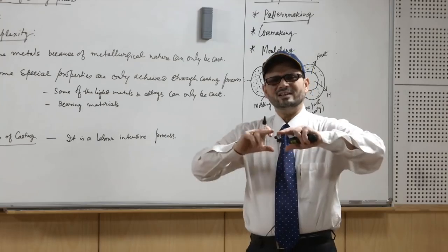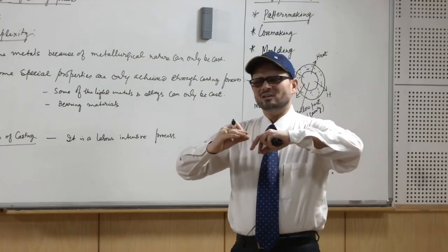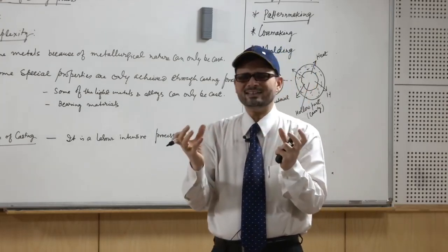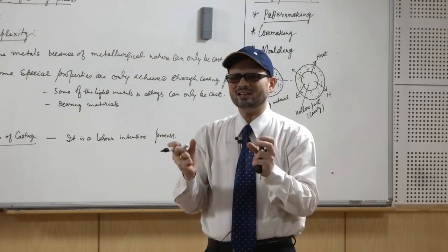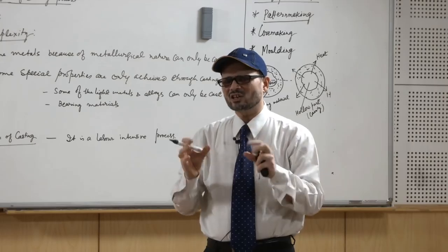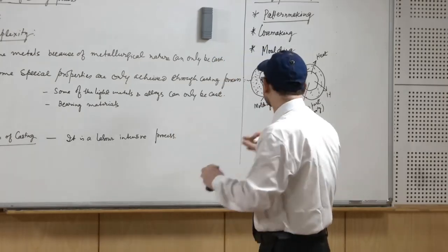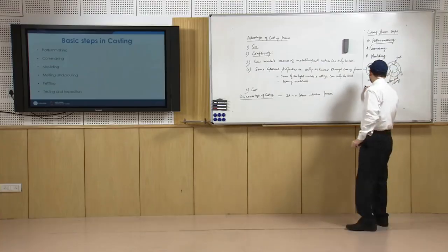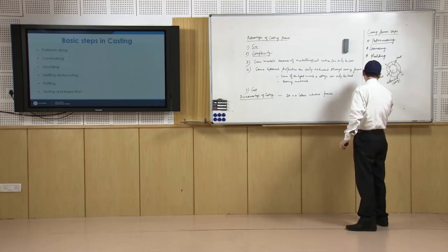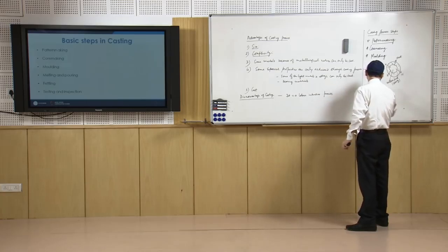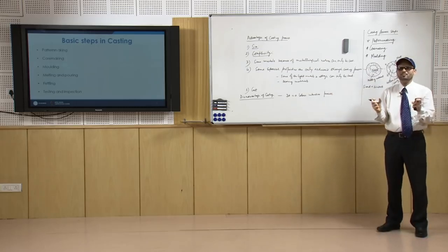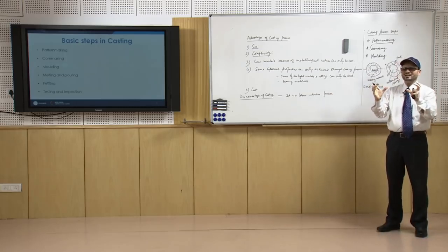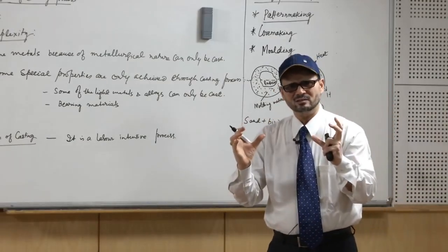For that, it has to be first brought to a state where it can have the cohesion. So, in most of the cases you are putting the binders with the sand, so sand will be used with binders so that it has the cohesive property and you can give any shape to it.